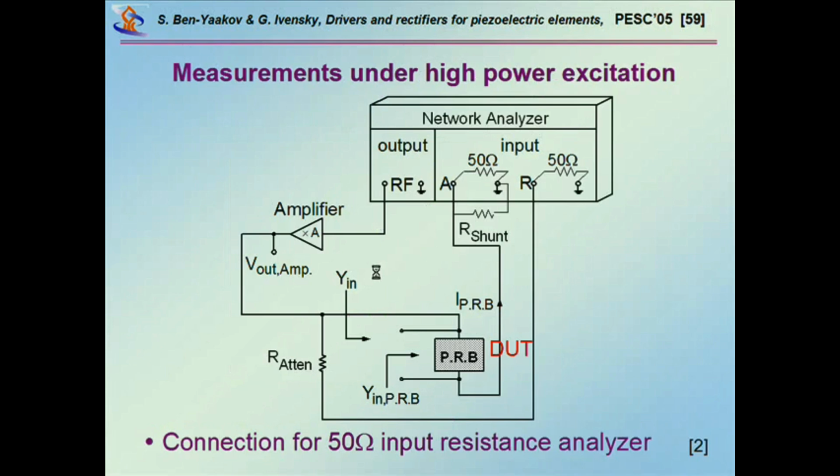So typically what we'll do is, if we start with the network analyzer, obviously in no way will the excitation of the output be sufficient. We're talking about high voltage, in some cases hundreds of volts. So you do need an amplifier.